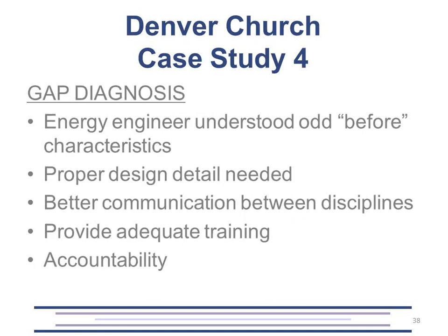Luckily, none of the problems lasted long. The analyst had first-hand knowledge of the existing system operation and therefore modeled it accordingly. During verification of the new system, the analyst noticed the valve and piping issues we discussed, and since those issues were caught, they were corrected. But if the installers had communicated the discrepancies prior to their workaround, they wouldn't have had to repipe it 3 times. If the development team had communicated to the analyst the proposed value engineering detail, the impacts could have been addressed at that point, and it would have provided a less costly alternative solution.